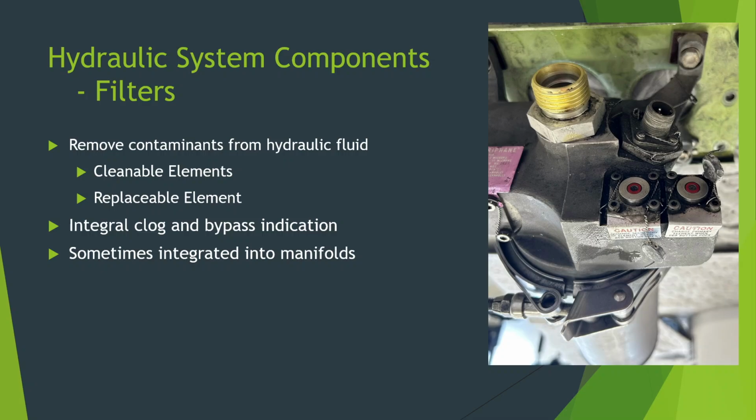And as it gets further and further clogged, there's a point where that pressure differential can get high enough that it can cause one of these impending bypass pins to pop. Now the reason this one has two is you saw it after a post-service bulletin or a post-mod, where it just has a single element.